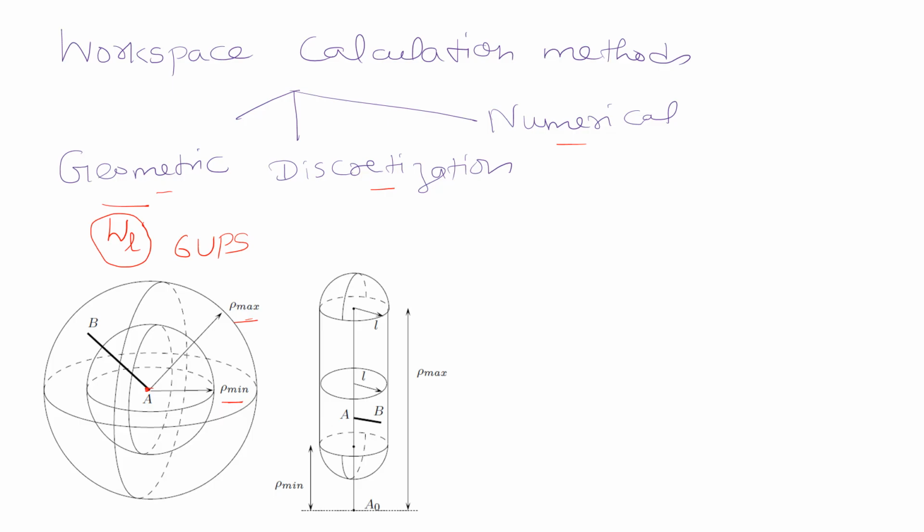If we further assume that the orientation of the end effector is constant, then each leg constrains the operating point to lie in a similar region, whose center is obtained by just translating that particular A_i by a constant vector. So the workspace of the robot is then obtained as the intersection of all W_i here, right?